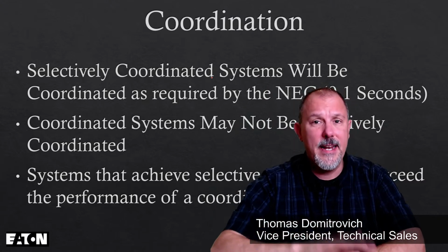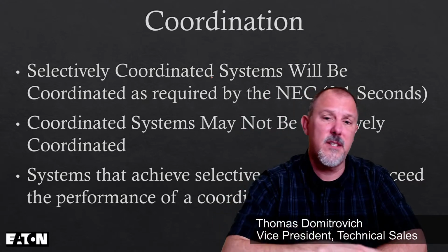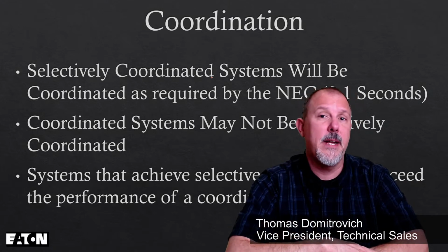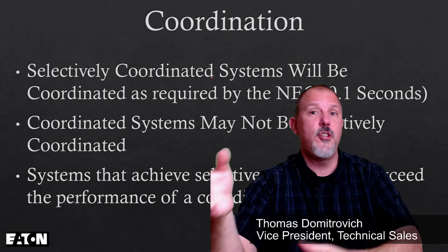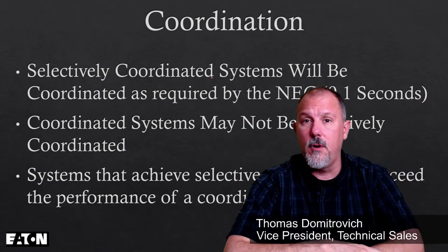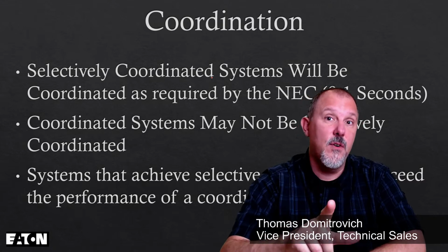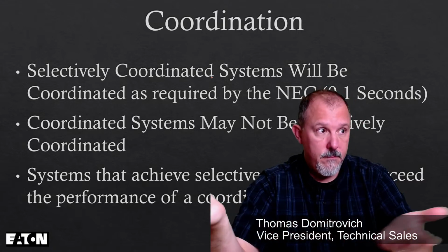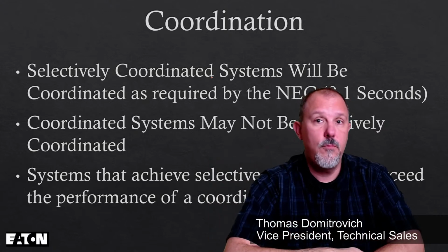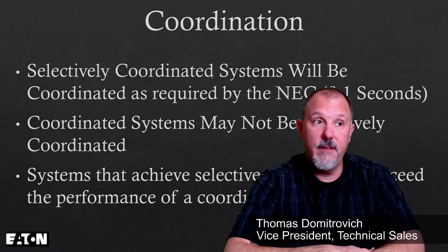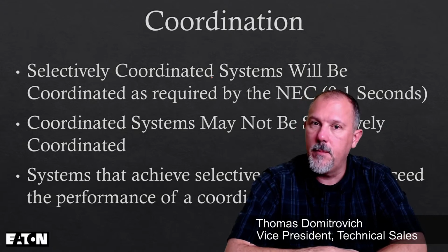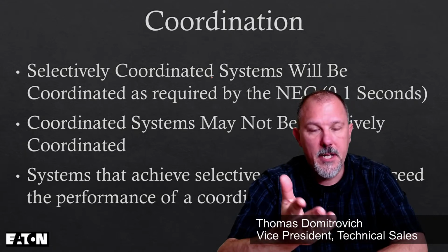Set it, forget it, go away. You'll use the smallest devices that you could possibly use. You'll probably be in standard thermomagnetic circuit breakers, which would mean you're in smaller panel boards. You'll use smaller conductors overall. Be mindful that if your goals are reliability, then you probably should invest a little time and money, but you don't necessarily have to from a code perspective in some applications.